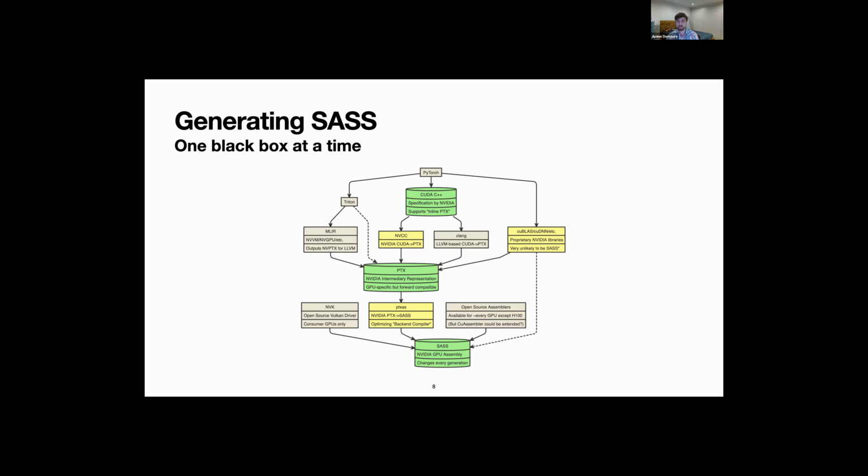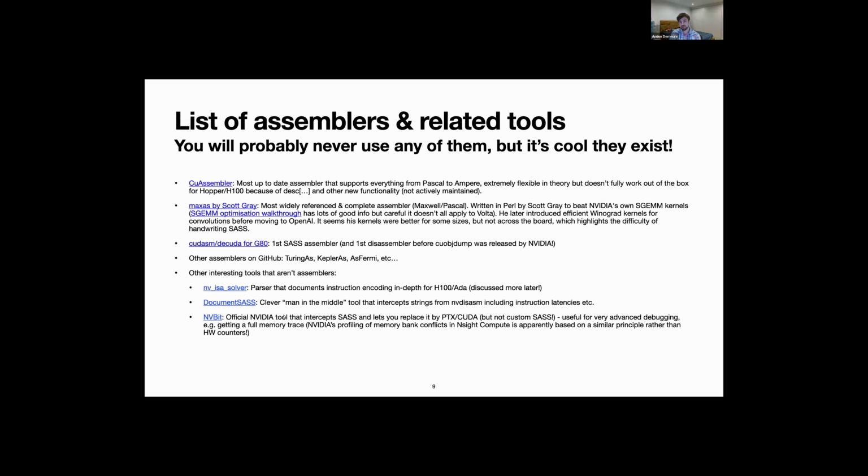You can look to the chat logs of their IRC channels and the code and so on in order to understand some of the very final details if you really want. Obviously, that doesn't tell you everything because the driver sometimes doesn't even need to know about the way the hardware works, but it's an interesting other source of information. So this is just a list of the different assemblers. QAssembler is kind of the most modern recent one, but unfortunately it's not been maintained either. MaxAs by Scott Gray is the most well-known one.